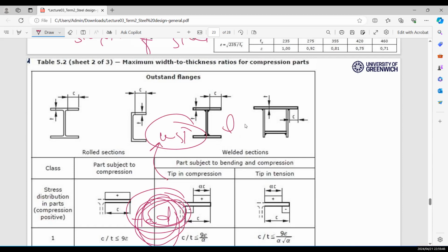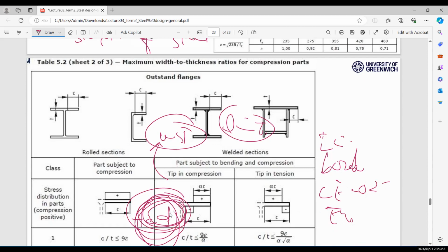But I don't know why your professor is using the limit state method, because if you study the Eurocode book which I have mentioned, Eurocode 2, you mostly do not see this parameter while designing concrete. But it is not a big difference. You can use any of them. For example, the characteristic strength of steel is 500, and the design strength is 435. So it doesn't make a big difference.